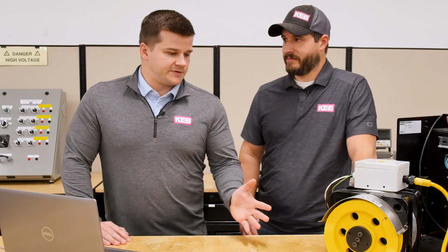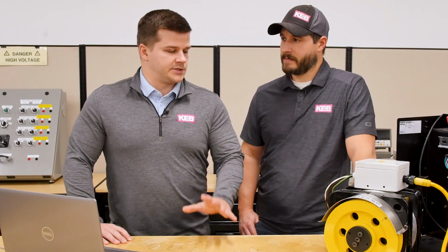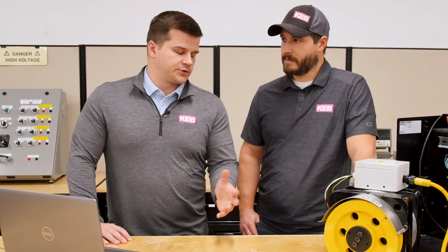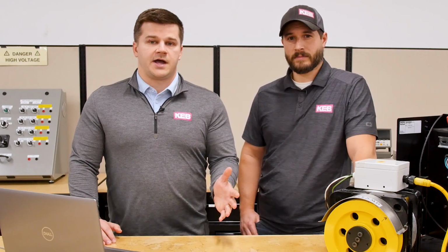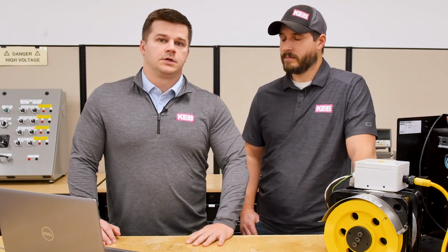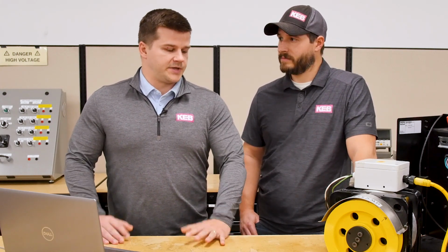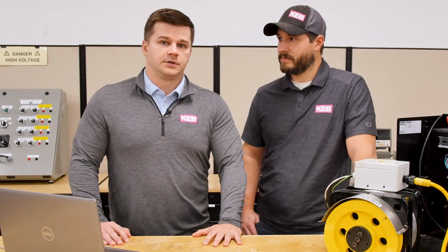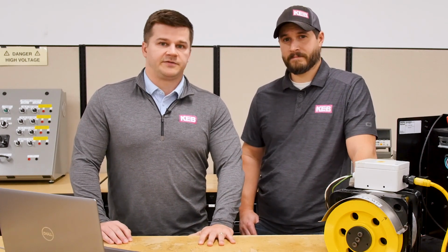Now, how would you go about understanding the encoder offset and maybe remedying any issues that might occur? It does have to stay constant, so one common reason it comes up is because the encoder is slipping on the motor shaft, so that would have to be addressed first. But otherwise, in general, on the first time you run the motor, you're going to have to learn the offset before you can spin the motor. But then as long as the encoder is mounted properly to the motor, you're good to go and you can run for the lifetime of the motor.